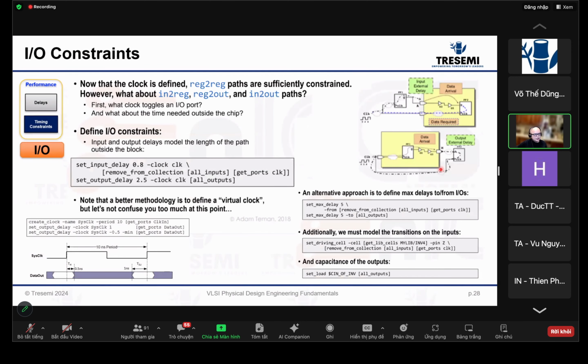In addition to the major setup and hold time constraints, the previous setup checks are covered for register-to-register paths, meaning flop to flop. But in a system, your input arrival time is not going to be the same for chip to chip.